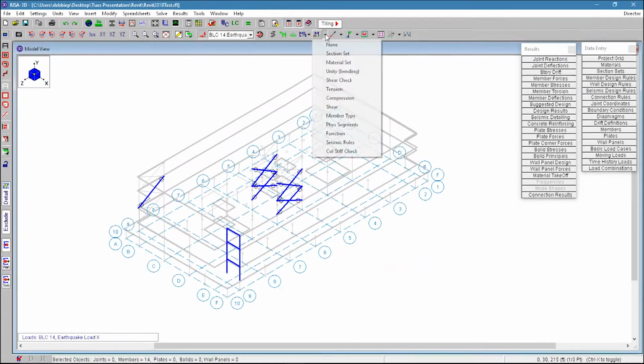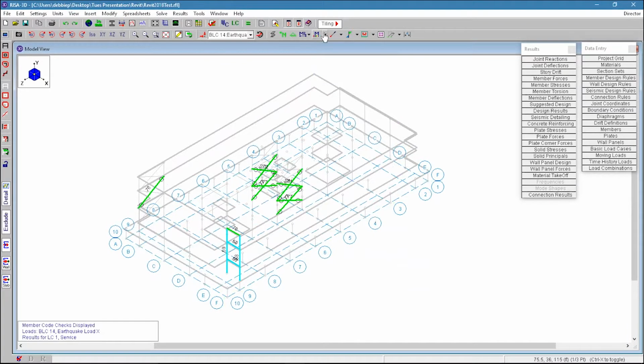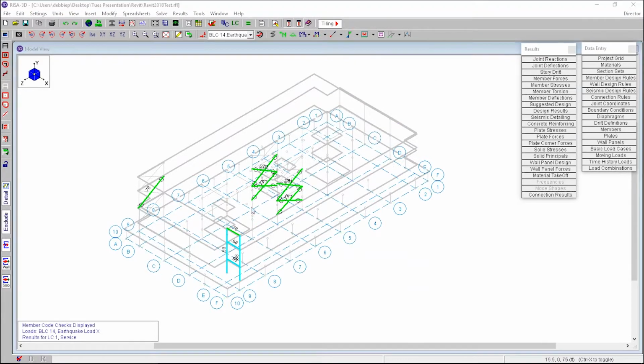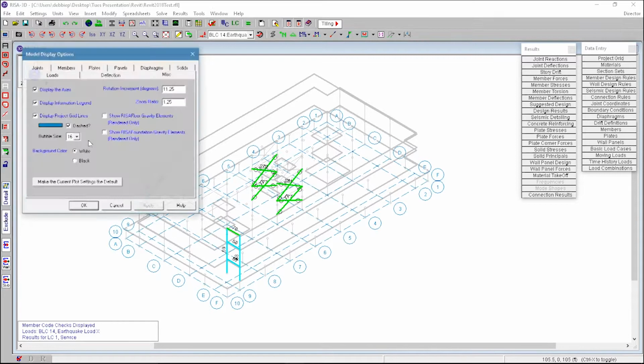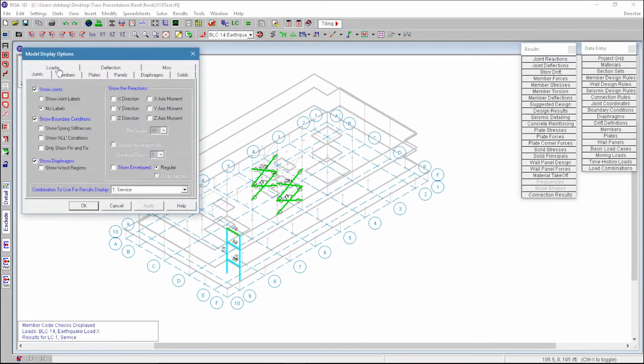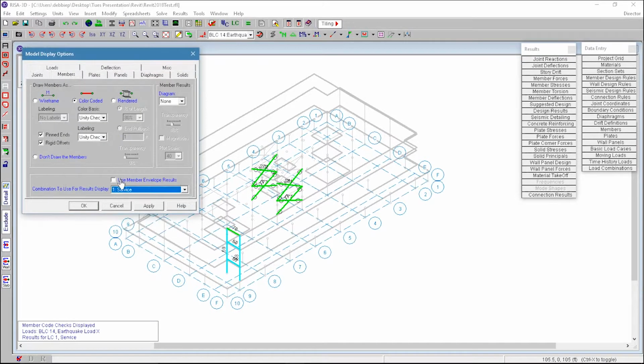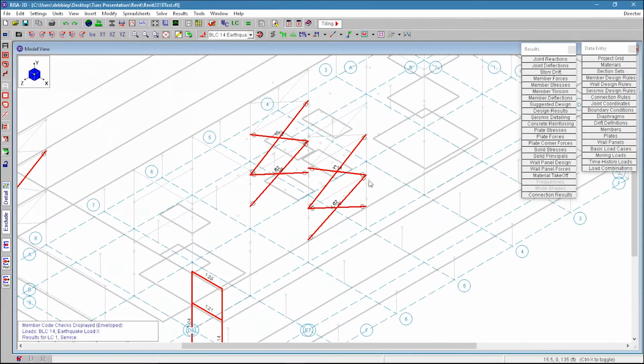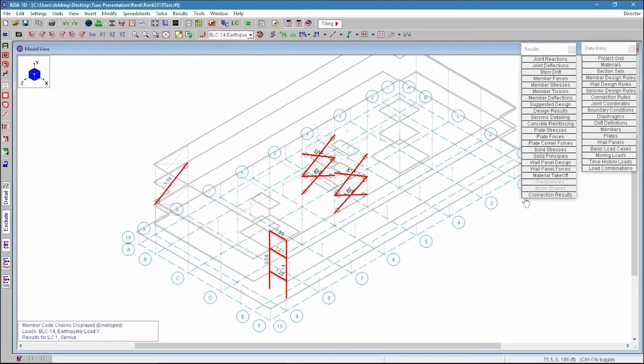We can also show this color coded too. RISA is a very graphical tool, so you can turn that into color coding and it'll show us any of the bending you need to check or what was causing that to fail. So we're looking here at a single results here. We can also look at, just by going back over to the members, we might show ourselves as the envelope results. And we see these are the envelope results that are failing. Not by much, so you might want to size things up based on what they need there.